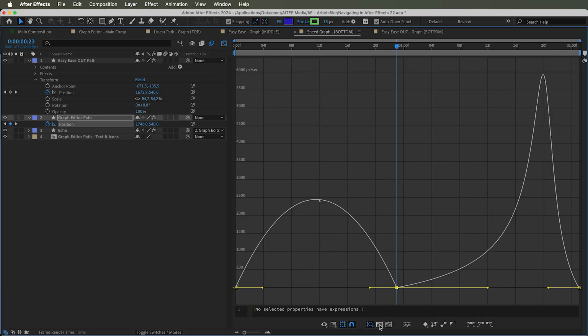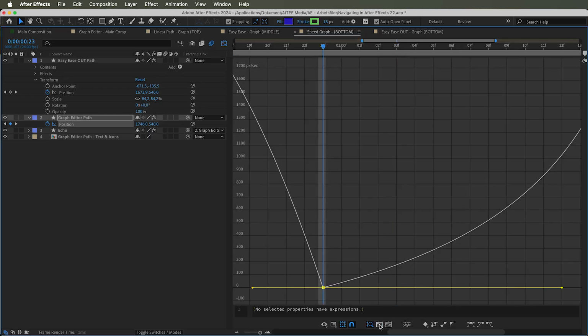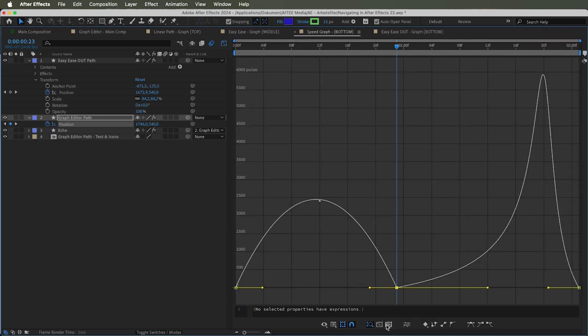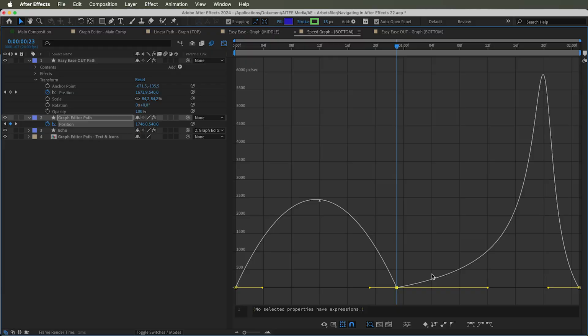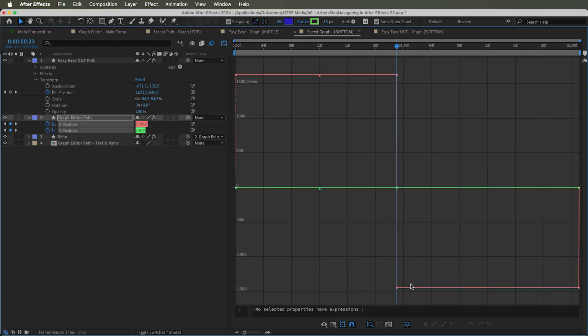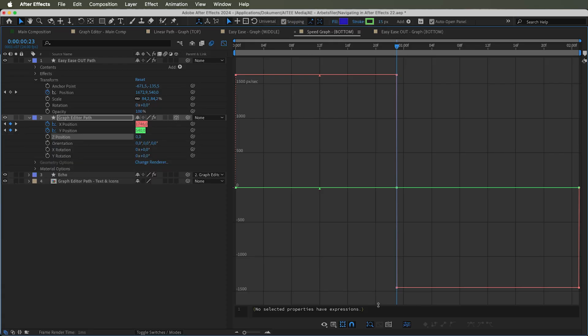With the two graph icons on the left, we might toggle visibility while either focusing on just one of the keyframes with the left icon, or we might also zoom out for all of them on the right one. Next one here is just a really handy one when we are coming in for the next graph, the value graph. The separate dimensions kind of splits position values in X, Y, plus the Z one if we're actually turning on the 3D space as well.